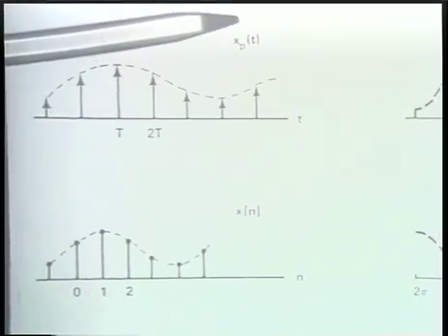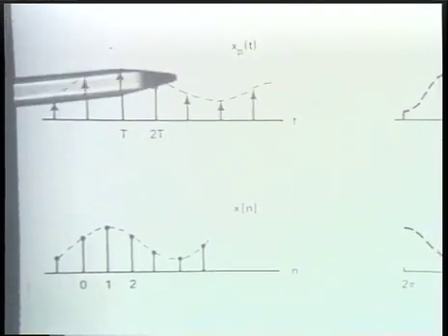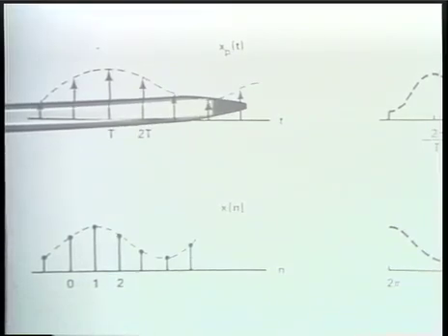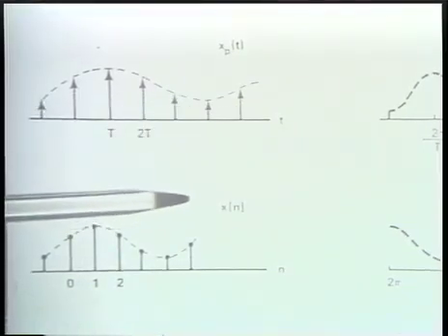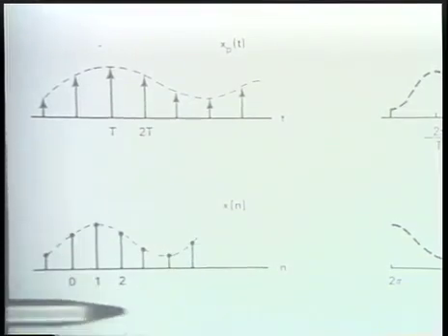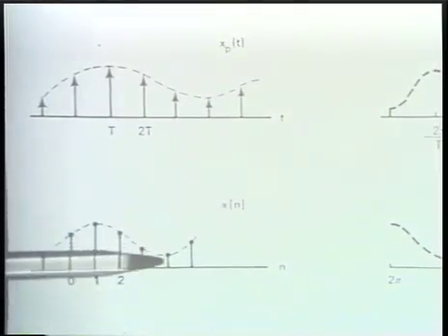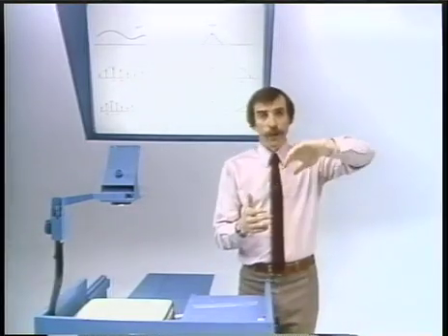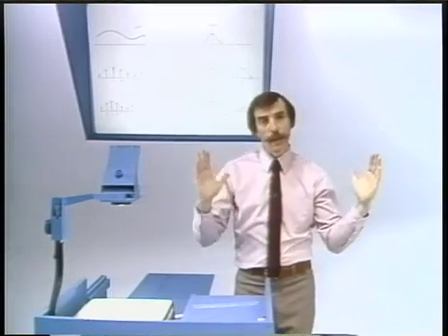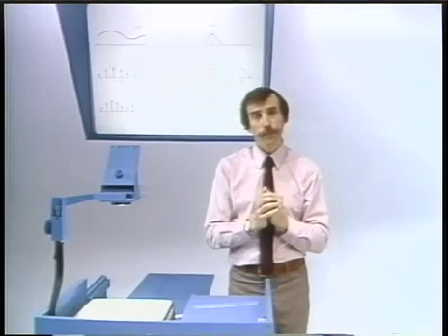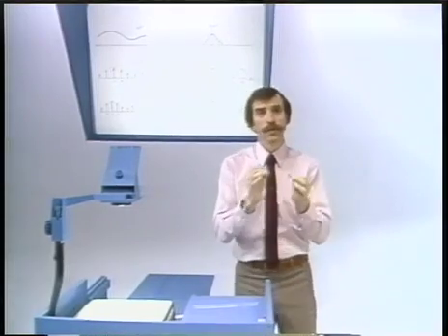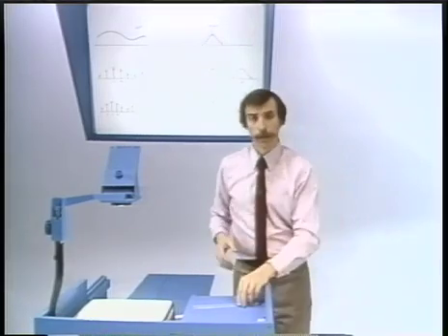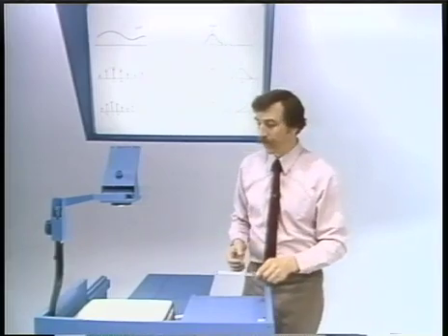To stress that another way, if the sampling period were doubled so that in this picture the spacing stretched out by a factor of 2, nevertheless, for the discrete time signal, the spacing would remain as 1, and essentially it's the envelope of those sequence values that would then get compressed in time. So you can think of the step in going from the impulse train to the samples as essentially a time normalization. Now, let's look at this in the frequency domain.